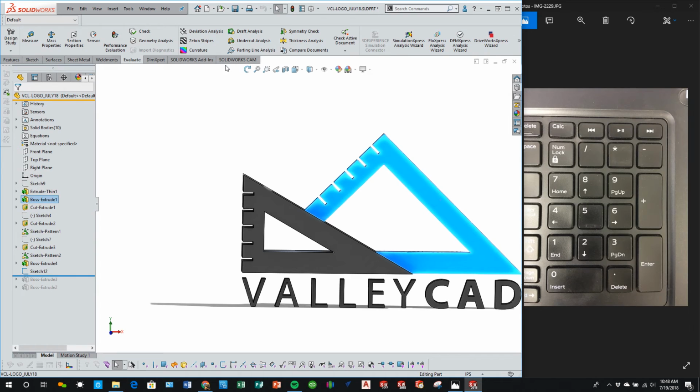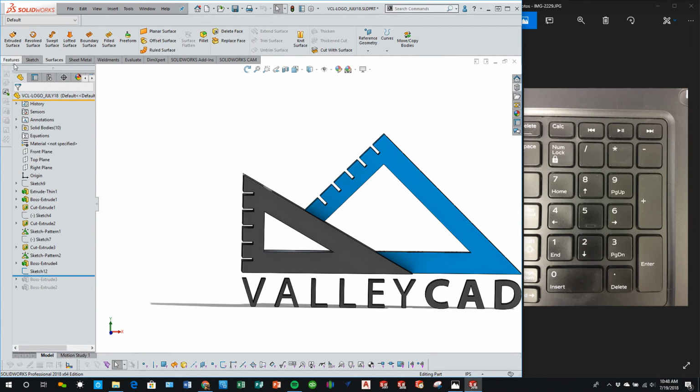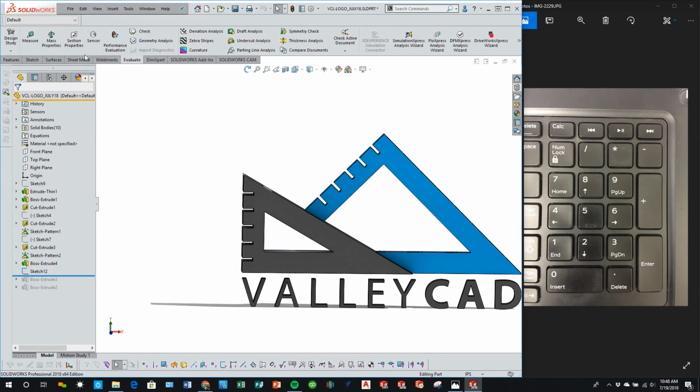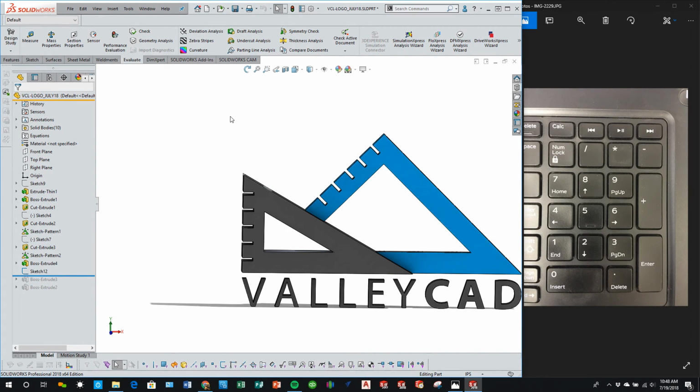And so once again, because I use it all the time and I don't want to switch between features or surfaces, these different commands, and then switch to the evaluate tab, I just found myself pushing the letter M. I don't have to take my hand off the mouse at all. All I have to do is just use my left hand, push the letter M or whatever key binding I choose for this, and it speeds up my process. Creating shortcut commands on your keyboard is here to speed you up.